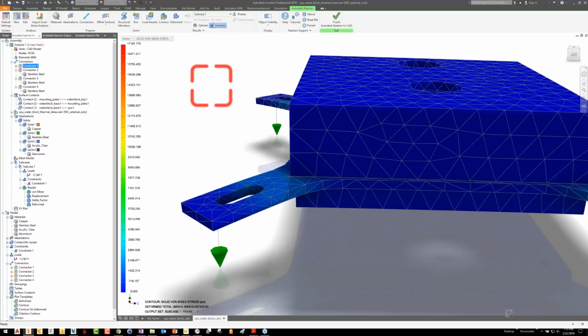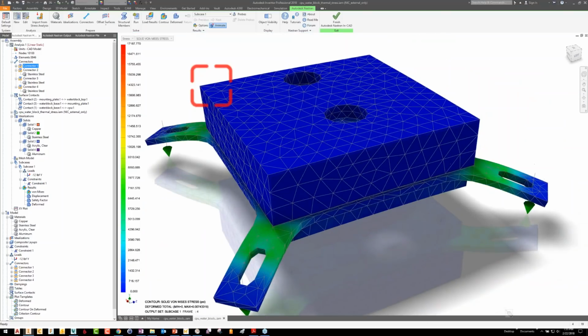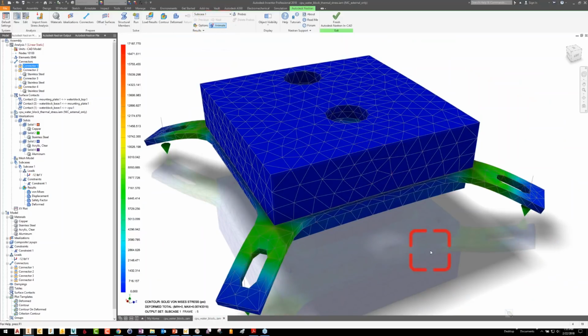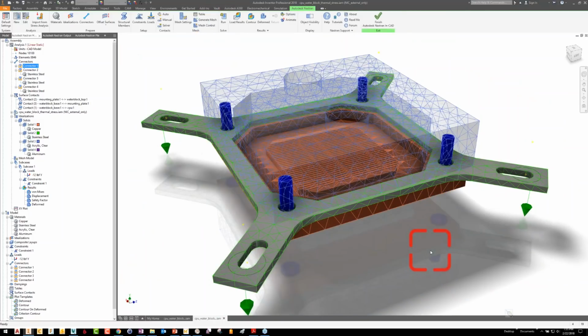So I've added some realism into the model, but you could see how my initial failure, because of adding the surface contact, that's the kind of trouble that surface contacts are going to cause you. You now have to worry about constraining the parts that aren't bonded to others. And that's also why I say build simple and add complexity as you go.